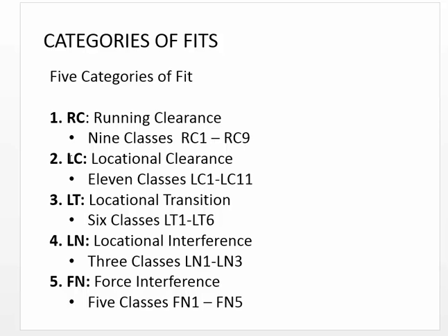LC stands for locational clearance. That's a clearance, but it's a smaller clearance. There are 11 classes of locational clearance, 1 through 11. LT stands for locational transitional. That means that it could be a little interference, it could be a little clearance. It depends on whether or not the parts are manufactured at max material condition or least material condition or somewhere in between.